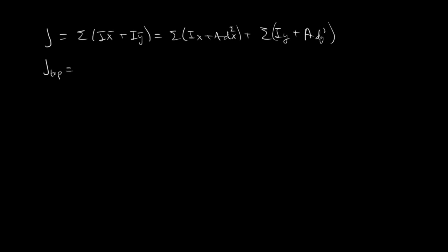So for the top weld, with respect to the centroid, we can calculate this as 100 cubed times t over 12 plus 100 t, which is the area, and we'll take the distance to x, which is going to be the middle of that weld group minus where the centroid is, which is 20, and that's squared.